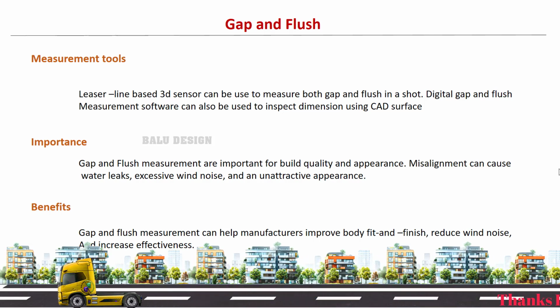And importance: the gap and flush measurements are important to build quality and appearance. Misalignment can cause water leaks, excessive wind noise, and an unattractive appearance. So for appearance purposes also we are majorly using this.